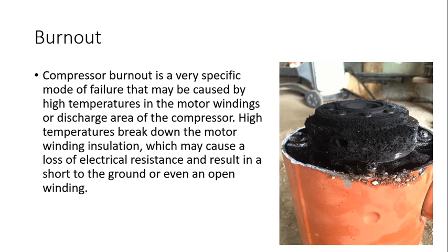Burnout. Compressor burnout is a failure of electricity inside a compressor, which will cause acid to build up, and you can see what the inside of a compressor looks like. When you have a compressor burnout and you lose the compressor, you can't just remove the compressor and put a new one in. The inside of the system needs to be cleaned out.